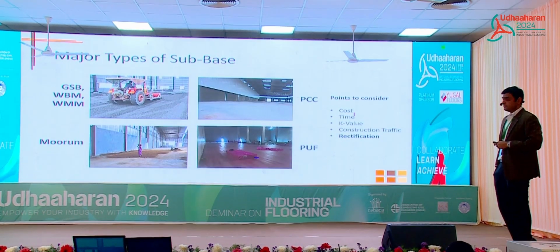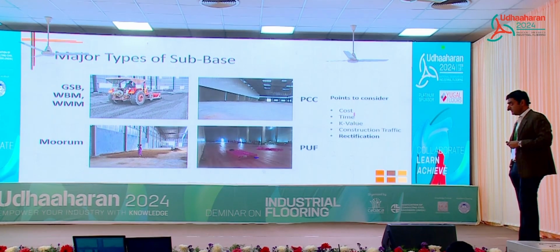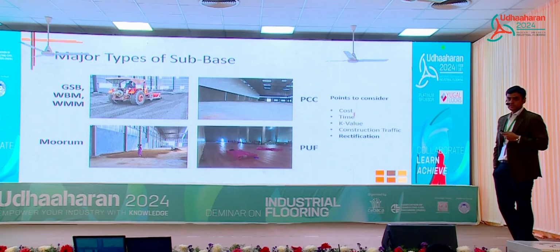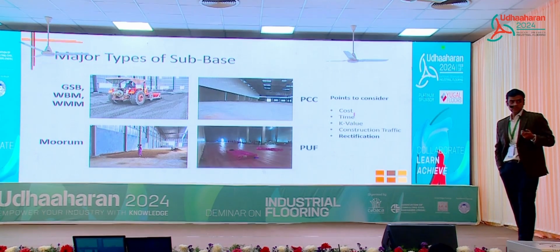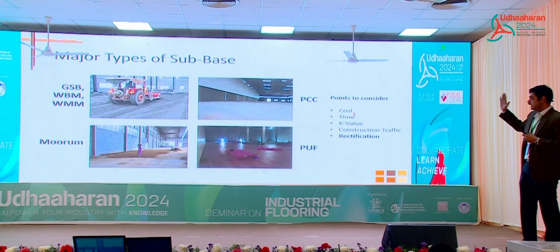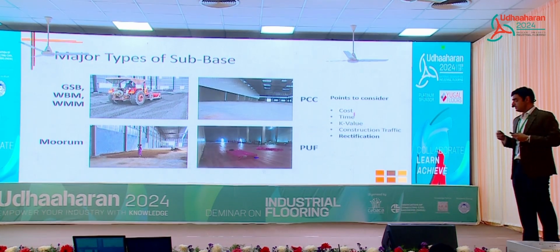Now, what are the major types of subbase? The first picture is GSB, granular subbase, water-bound macadam or water mix macadam. This is something that is most commonly used, and this is what we also recommend, and I will explain why. Second type is plain cement concrete, PCC.